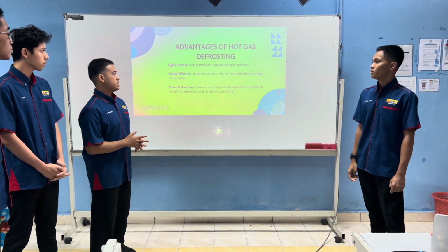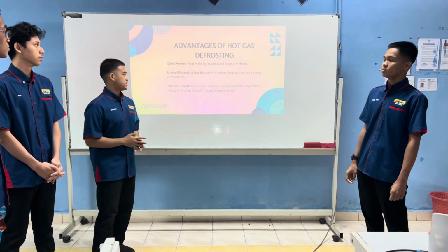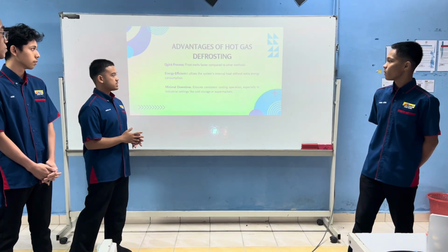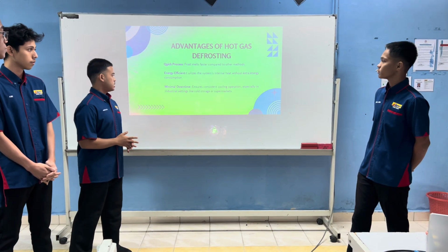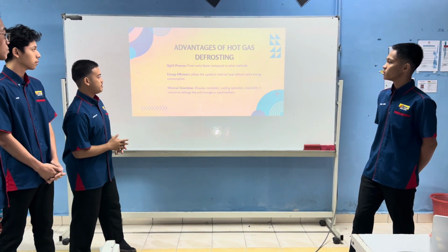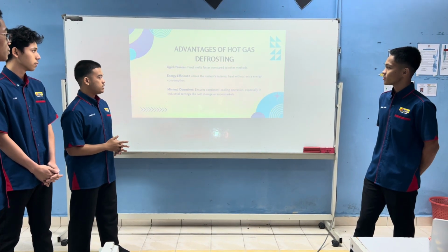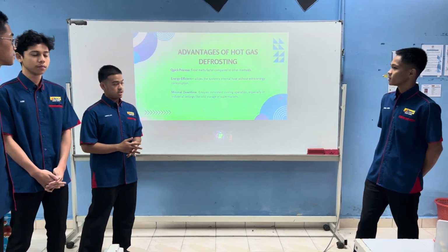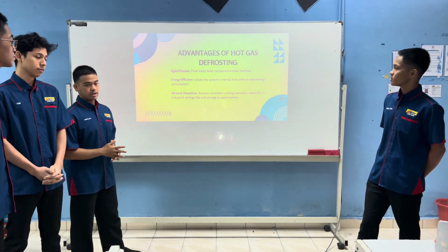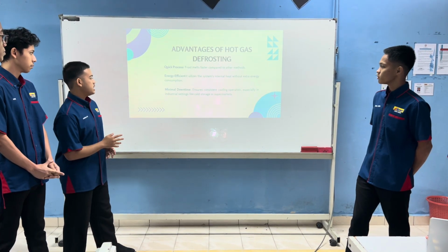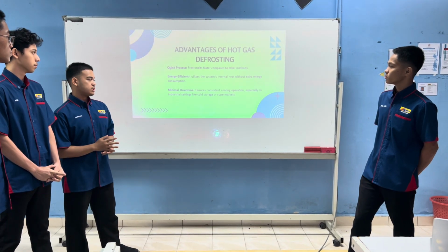Okay, these are the advantages of hot gas defrosting. First of all, it's a quick process. It removes frost much faster compared to other methods. Second, it is energy efficient, utilizing the system internally without extra energy consumption. And the last one is minimal downtime. It ensures consistent cooling operation, especially in industrial settings like cold storage or supermarkets.